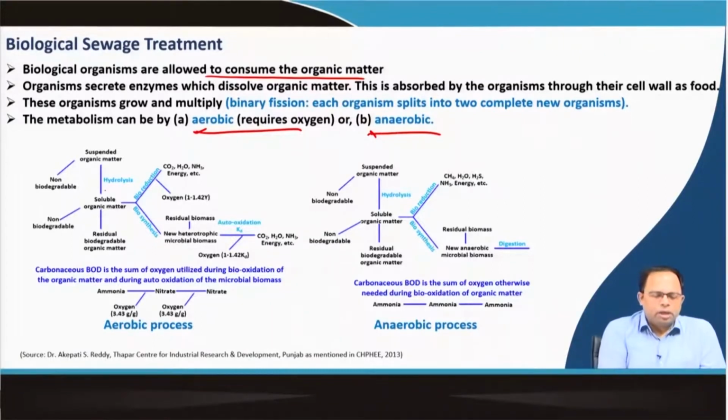So, we have suspended organic matter, and once it is mixed with water, we have hydrolysis, which is when certain chemicals break down because of mixing with water, and then we get soluble organic matter. This is acted upon by residual biodegradable organic matter, and we also have residual biodegradable organic matter in that particular sewage.